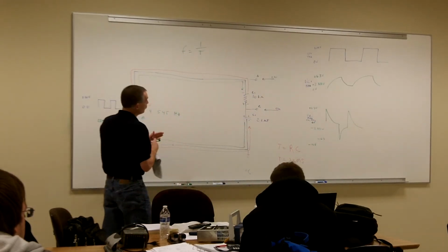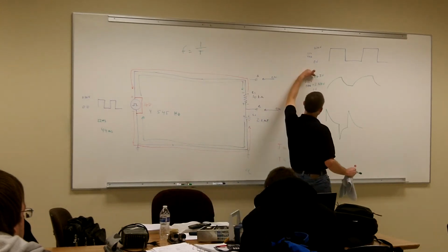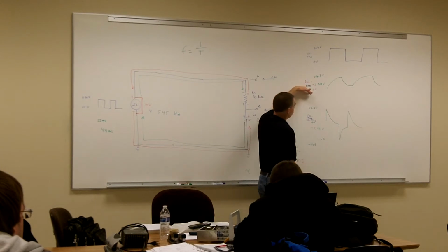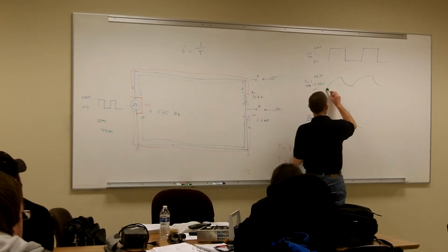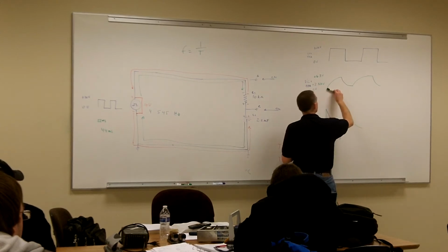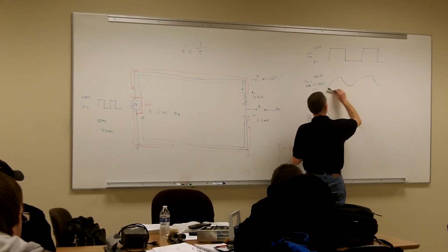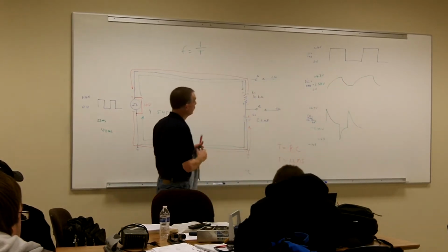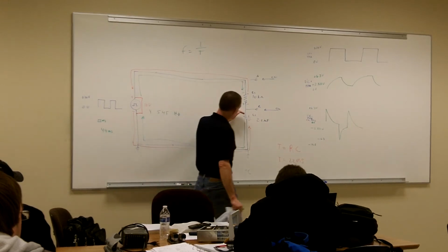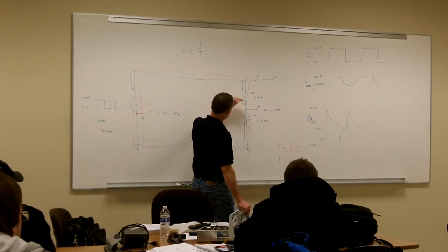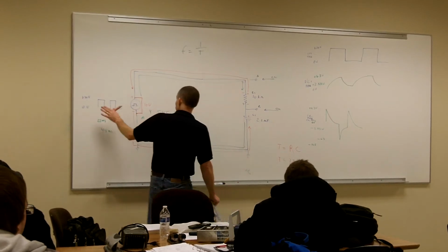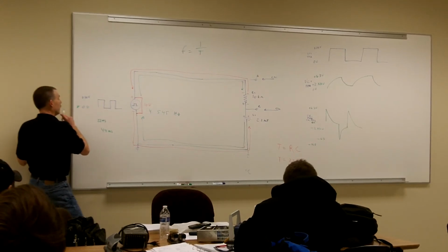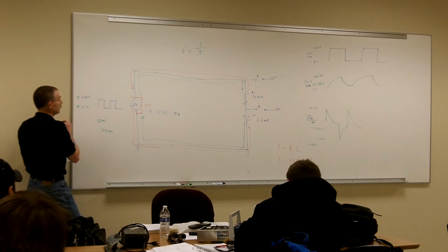So if we don't give it its full time constant, it's never going to reach its maximum charge, and it's never going to discharge fully. It's going to start out at 0 when I first apply the voltage, but then it's going to stabilize between these two voltages. It's either taking in energy or putting it back into the circuit depending on where my function generator is. When you're setting up your labs, make sure you're setting it up for your 0 volts and your plus 10 volts.